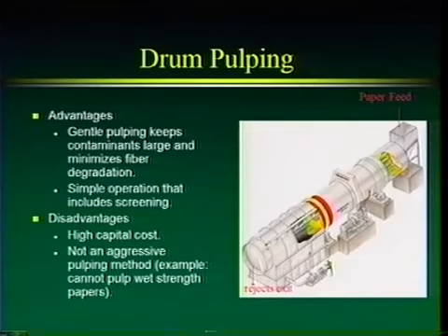Okay, this next picture is going to give us a nice cutout overview of the pulper. The paper feed comes in right here. It's dropped down. You can see here these yellow things are baffles that are picking and lifting the paper up and dropping it. Then we've got our low consistency zone. We've got our spray where our water is, where we're decreasing the consistency. The good material comes out the bottom, out through the screen, and then the rejects exit out this back and are thrown away.